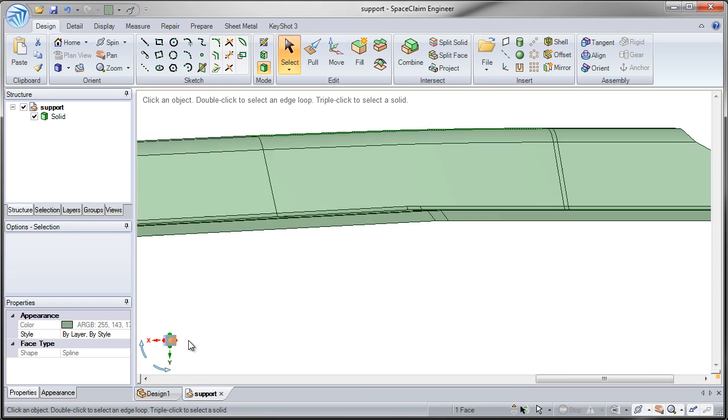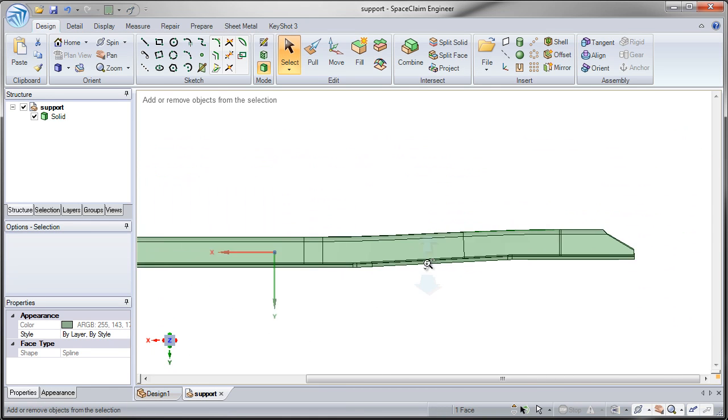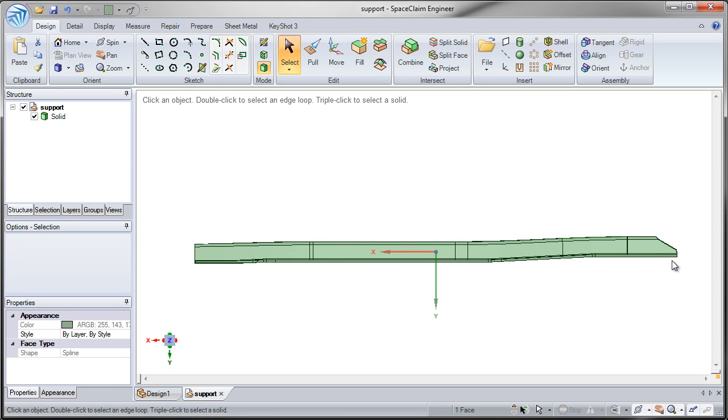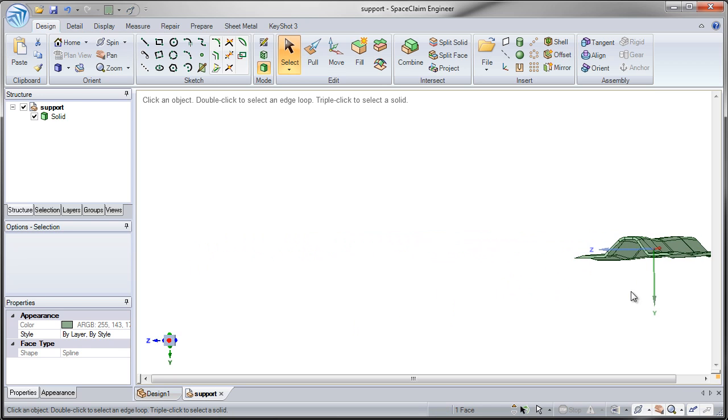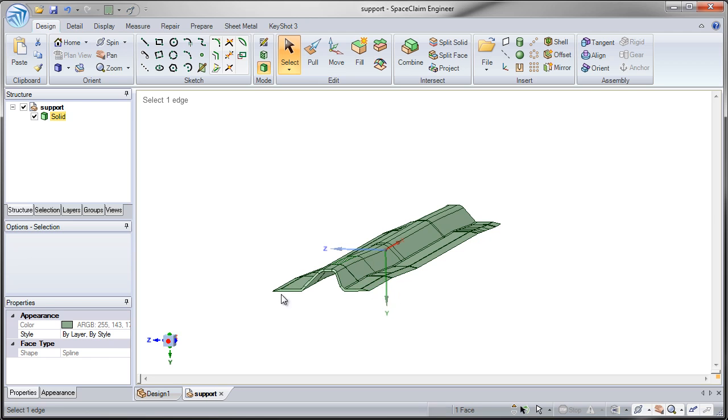And if we use the Z direction to rotate this, it simply goes down a path. Goes across, down a little bit, across, and down again. So what we could probably do is simply sketch this basic profile and sweep it along to get this profile.